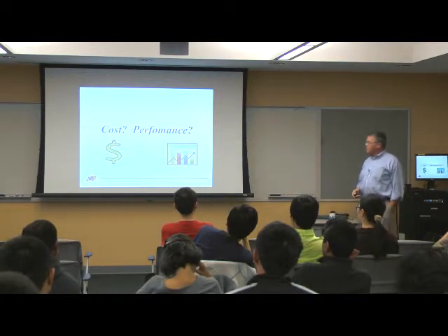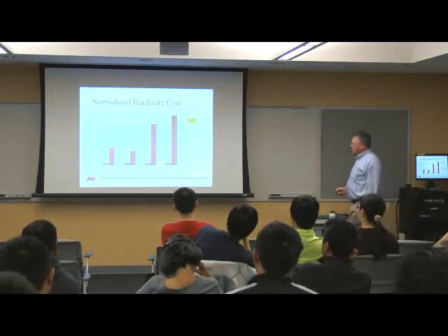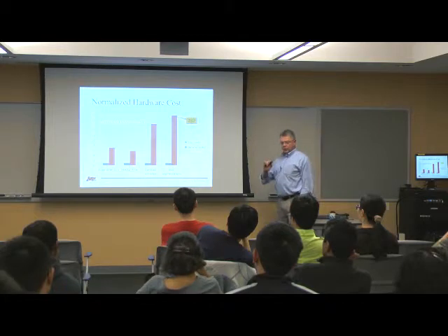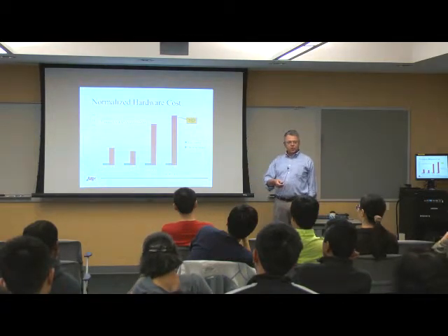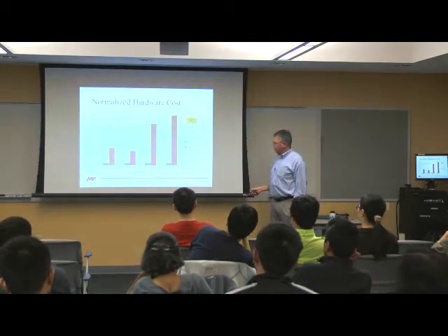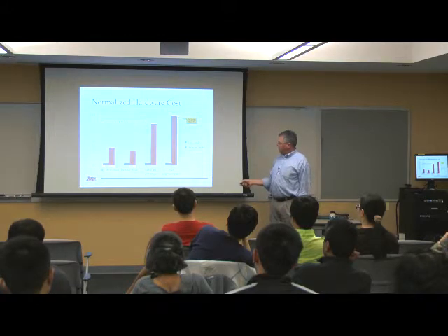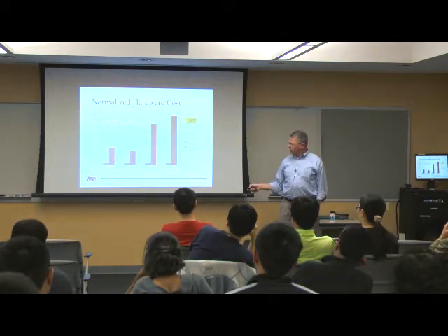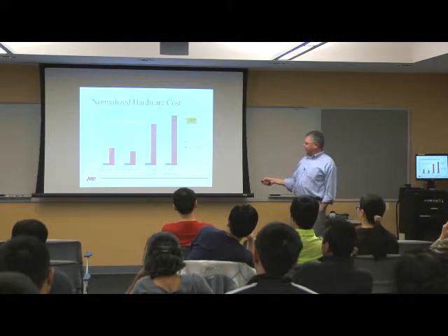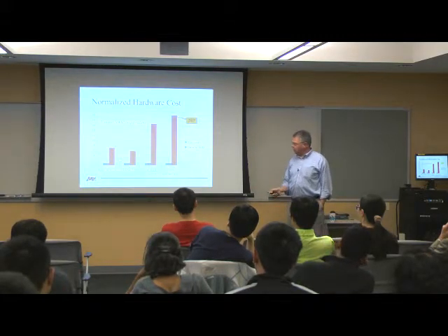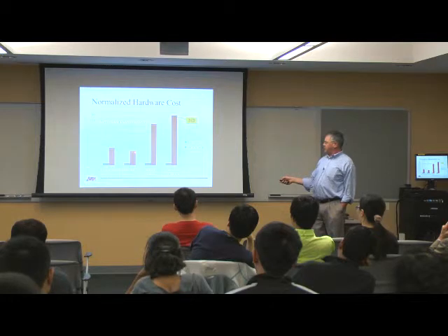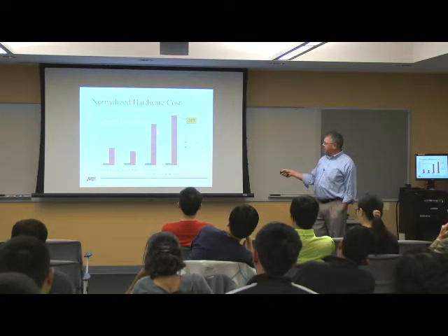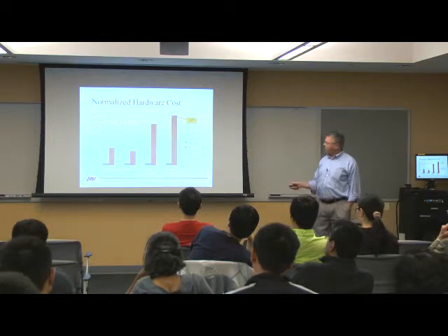Okay? From a cost point of view, here's the difference for those 4 implementations compared to a conventional implementation. For the edge detector, this is all normalized to the stochastic implementation, the blue bar. The edge detector is about 7 times more hardware than the stochastic. The median filter is about 6 times. The contrast enhancement circuit is about 16.5 times more hardware.